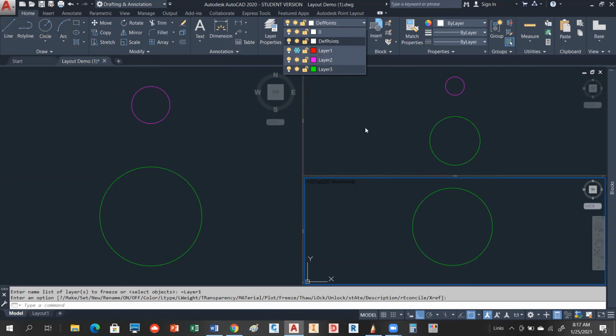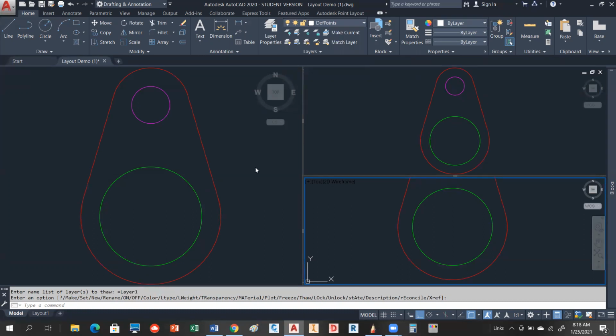So you're going to see when we get in the paper space, what they've done is they've added another freeze option, okay, freeze thaw. So actually we're going to also see alternate color options too. So you can have a base color and then an override color. So they've really done some pretty cool stuff when we get into paper space. So the thing is that this worked to a point, but it doesn't work across the board for everything people need to do. So back in release 12, programmers were probably barraged by users that said, look, this just isn't doing what we need it to do.